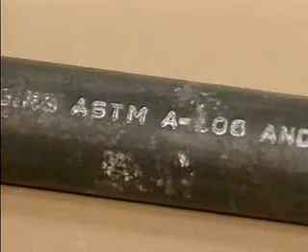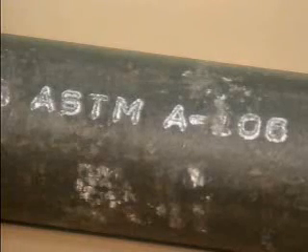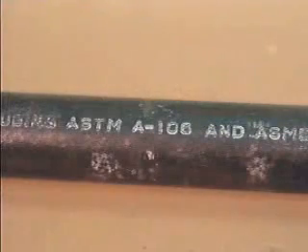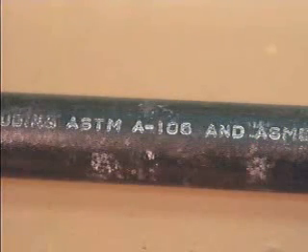Metal that contains iron, or ferrous metal, has an ASTM identification number beginning with the letter A. A non-ferrous metal identification number begins with the letter B. An ASTM identification number for PVC pipe typically begins with the letter D. A number, usually 3 digits, appears after the first letter. This number identifies the specific properties of the metal.